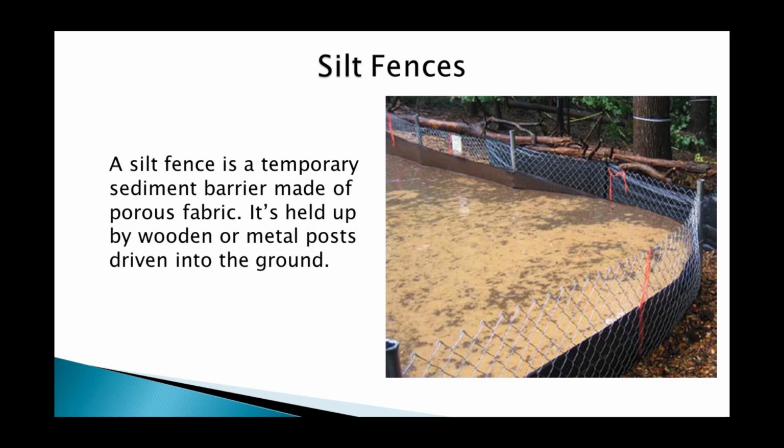On this view, you can see that there's been a lack of maintenance on this particular area. The sediment is almost all the way up to the top of the silt fence. It should have been removed by now. The requirement is that you cannot exceed half the height of the silt fence before you have to maintain it.